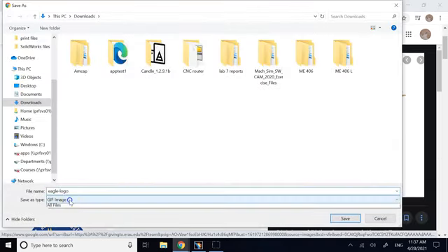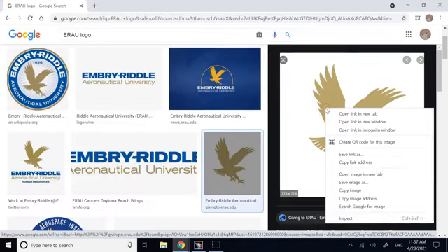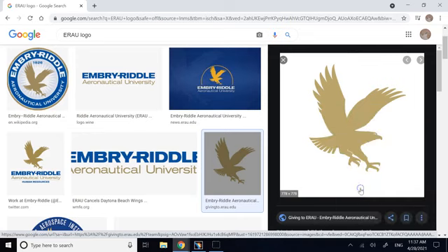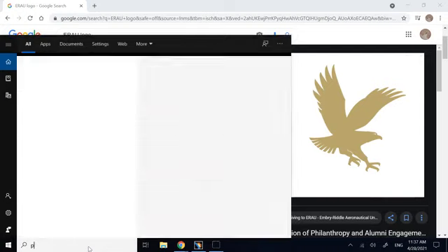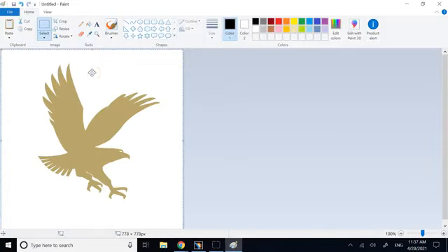Just make sure this image is a type of image that CATIA can read. Here it is a GIF image, and you have to make sure whether CATIA can read it. I'm not sure if it can do GIF. It can do .png and .jpeg. So what I'll do is probably copy the image, go to Paint, and save it in Paint.